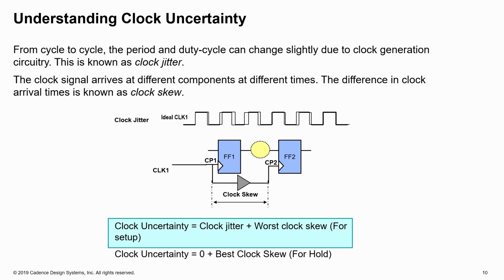And so the clock jitter is provided. Also, sometimes there is variance between when a clock arrives at different points in the design because of the buffers and everything that is inserted. Ideally these clock trees try to be adjusted so that there is not much variance in when the clock arrives at the different points, but it's inevitable because it is a real design.